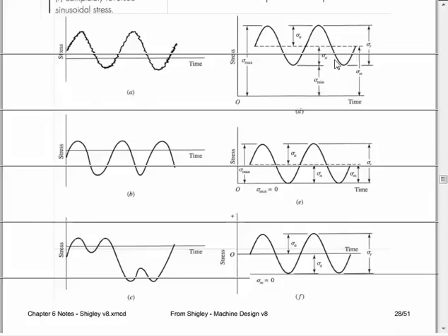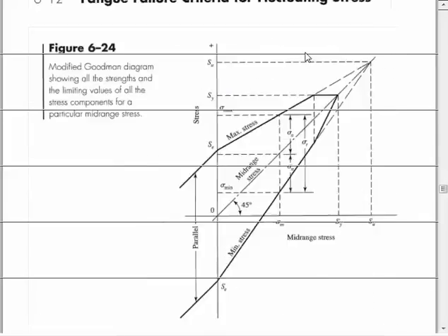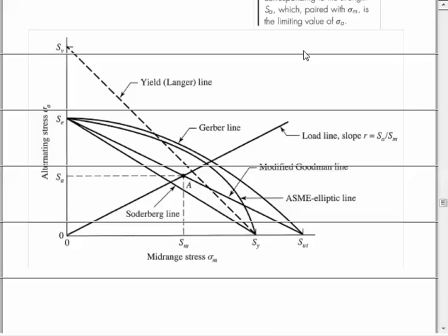How do we handle fluctuating loading since it is not handled by the SN diagram? We go to, and this is very messy, a diagram, and obviously there are lots of different theories on how these kinds of things fail, but the key is we go to a diagram where we plot mean stresses on the x-axis, and we plot alternating or the amplitude stresses on the y-axis.